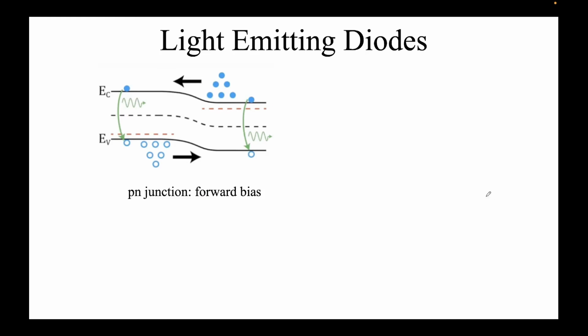That is, you apply a forward bias to the PN junction diode, which is what I have written over here. When you bias the PN junction forward, this is what you are seeing here. This is not an equilibrium, because this is the EFP, we have EFN here, and the rest, EC and EV, have been drawn. If this is applied to the negative terminal of the battery, some electrons come in, and then the electrons will drift across the depletion region. You can also see that the barrier is very low over here because the effective band bending is now VBI minus VA. That's why you see this very reduced, more or less flat region. So a large number of electrons will now drift across the depletion region and will recombine over here.